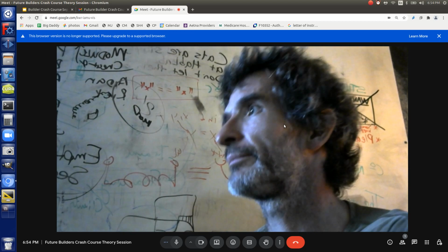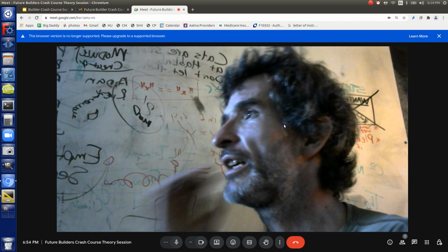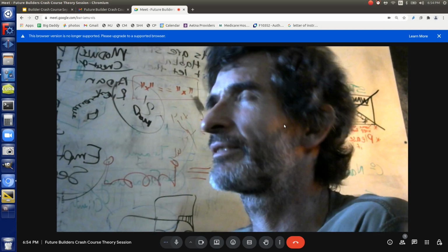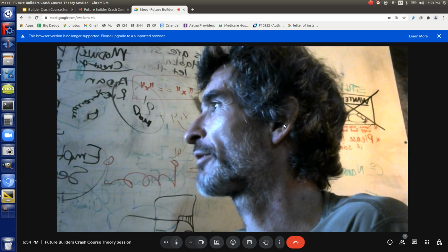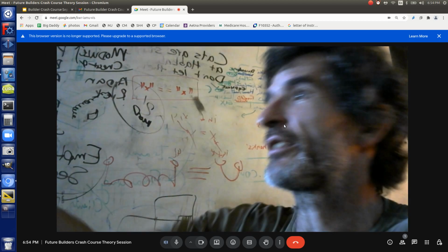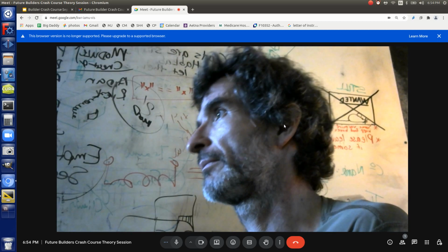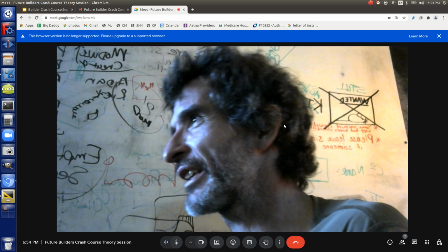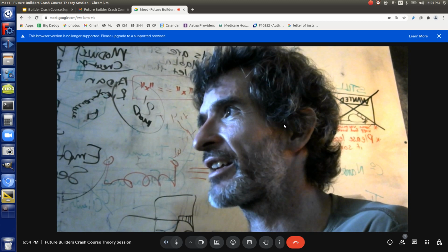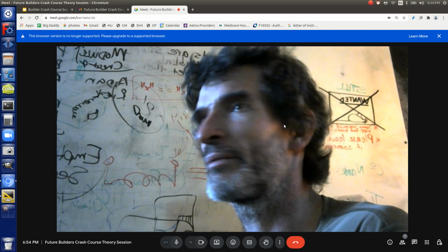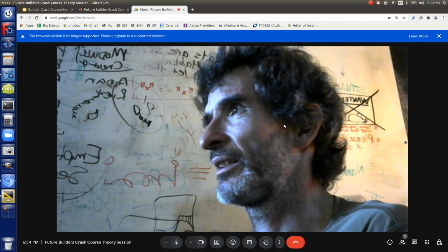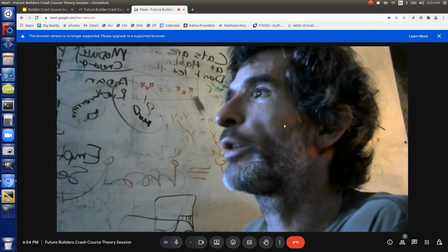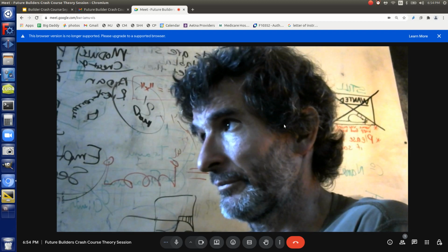2,500. Around there. If you take the max, say it's 100K for steel, like a mild steel. Well, probably the nails are going to be around 100,000 psi. So how do you get 2.5 thousand? It's 140,000. Yeah, I mean, that's like max. That's like spring steel, which is super hard. They're not typically making nails out of that. Probably nails are 70 to 100,000 psi. Let's say. So you're dividing that by the 1/8. So you're taking 1/8 of 140,000. So it'd be like 20,000.